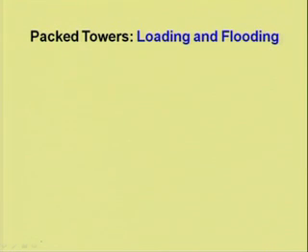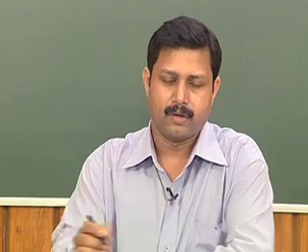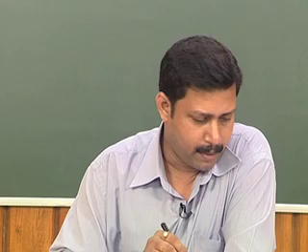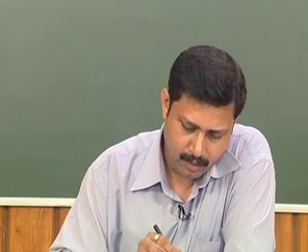Now, we will discuss the pressure drop in the packed towers. The allowable pressure drop limit for the packed towers should not be more than 1.2 kilopascal per meter of packing height.